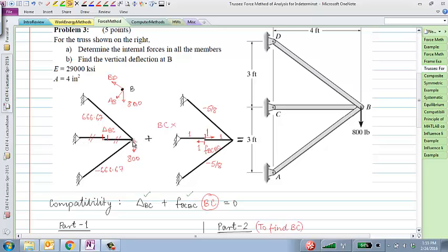For this particular problem, yes, that will work because this is laid out horizontally. If you find the horizontal displacement at this point, yes, you can. And actually, this will be a zero force member, so it won't have any displacement. It would be equal to that cut. But in general, if I have an inclined member, your logic will not always work.